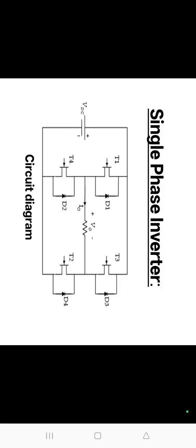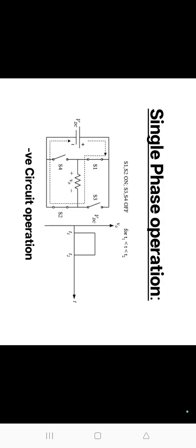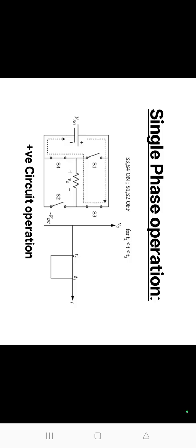During the time of 0 to T/2, the thyristor or IGBT, any switch, will be conducting with gate signal IG1. The voltage across the resistive load is Vs/2 due to the upper voltage source Vs/2. At t equals T/2, the thyristor is turned off by forced commutation and T2 is turned on.